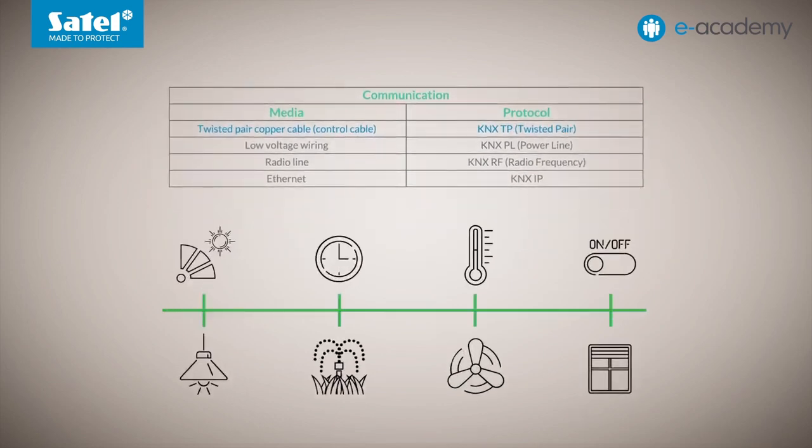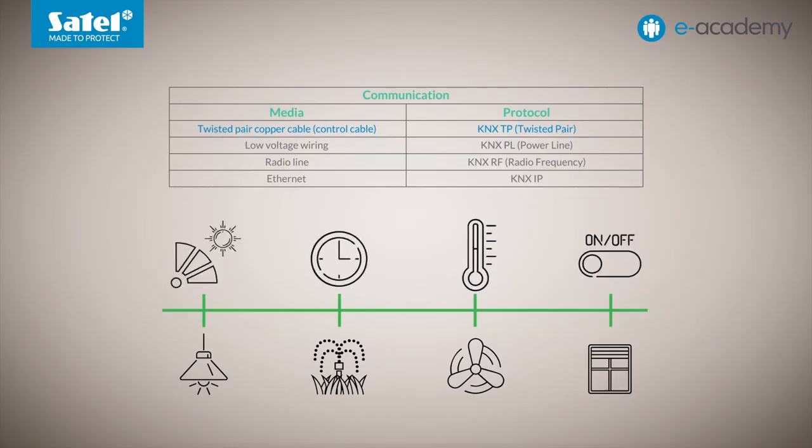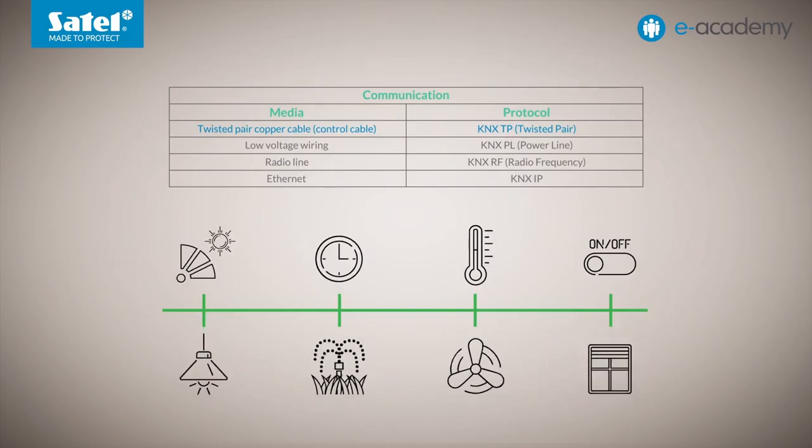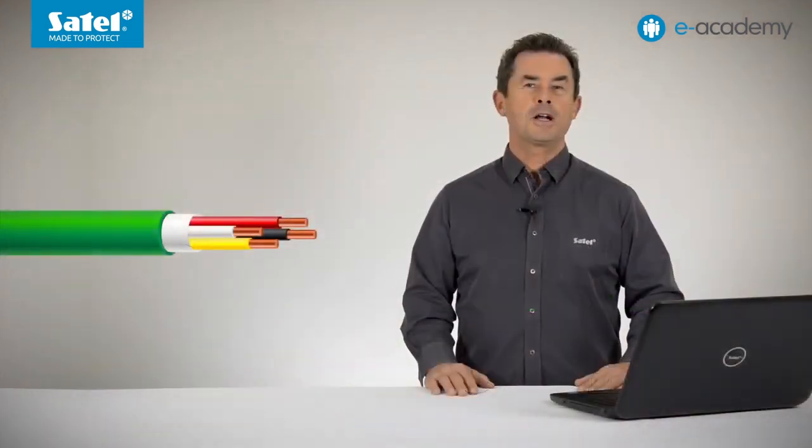In the case of a KNX TP installation, all the system devices communicate with each other over the bus. The devices that are connected to it can be divided into two main types, sensors and actuators. Sensors are the devices that receive signals from the outside. These can be, for example, simple buttons, switches, various parameter sensors, and multifunctional panels. Actuators, on the other hand, are various types of controllers that often manage the operation of numerous devices: switching, dimming, or roller shutter actuators, etc. In addition to these, the installation requires at least one power supply, but about that in a moment.